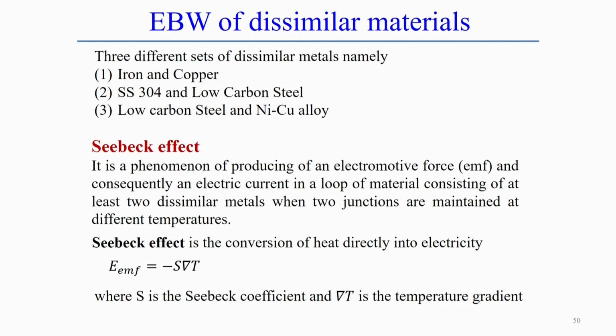So, the EMF, the electromotive force, can be represented as minus S times delta T, where S is the coefficient and delta T is the temperature gradient. So, the presence of a temperature gradient creates an electromotive force, that is the Seebeck effect, and that effect is responsible here for creating the deflection of the beam.